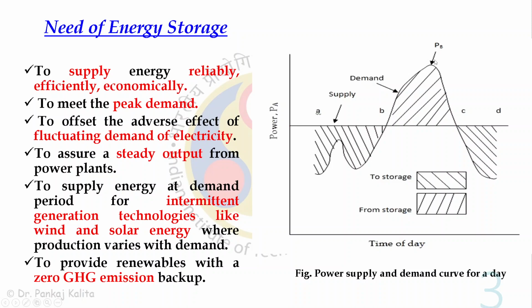So there is fluctuation in energy demand, and the renewable power production also fluctuates depending on sources like solar or wind, because they are not continuous supply, they are intermittent in nature. That's why this fluctuating demand requires energy storage devices to integrate with this type of system. So that is why we are studying thermal energy storage systems.